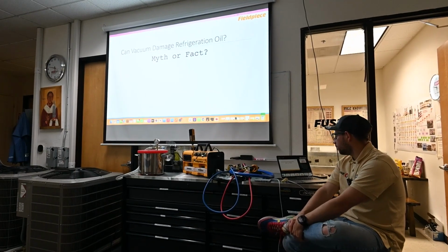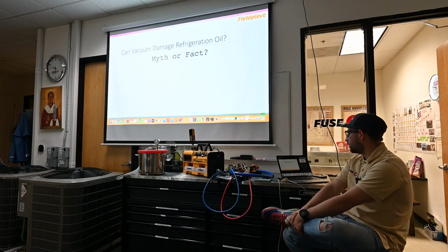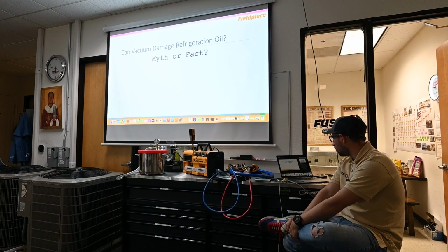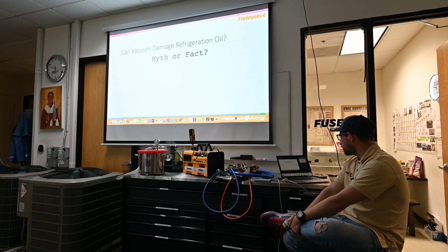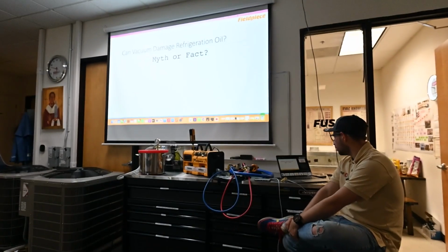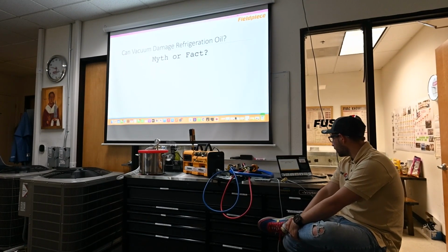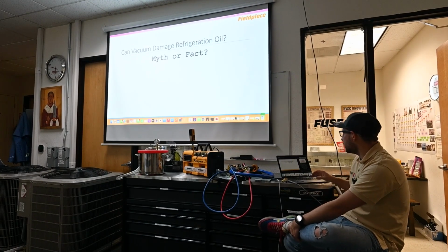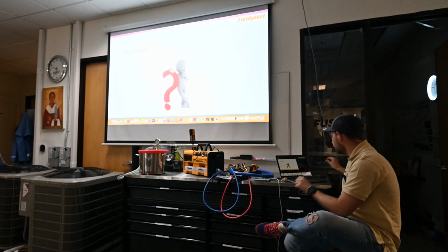Can vacuum damage refrigerant oil? Myth or fact? Will refrigerant oil be damaged by vacuum? No, this is a myth that has been going around the industry for some time. According to refrigerant oil engineers and testing, vacuum does not damage refrigeration oil until the pressure of the system is well below 10 microns. Busted. Okay guys, one more time.